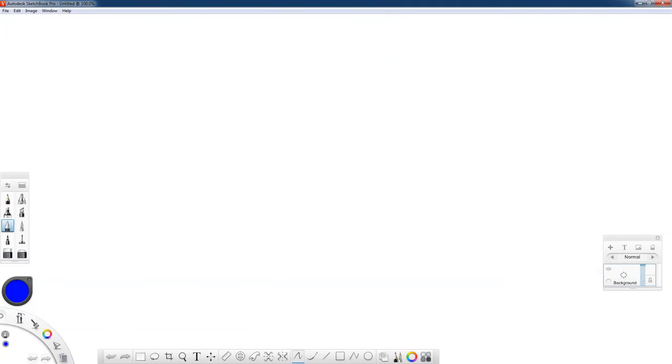Alright, so let's write down some of that. M is equal to EI over rho. We also know that sigma, with the sign in it, is minus z E over rho. We rearrange the first equation. We have rho is equal to EI over M.